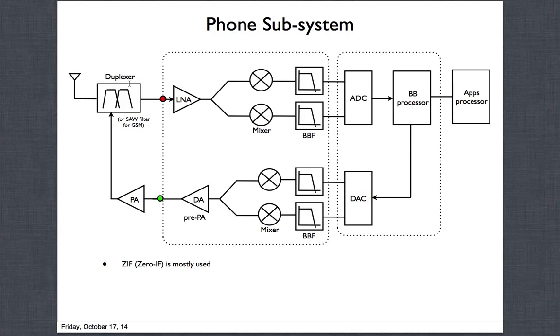Why? Because the transmit chain will also come to the duplexer, and it will go to the antenna through the duplexer. Whatever we receive from the antenna is also going to go through the duplexer and come to the LNA. Since these are two different frequencies, you might say, hey, they are different. Why do we need a filter?